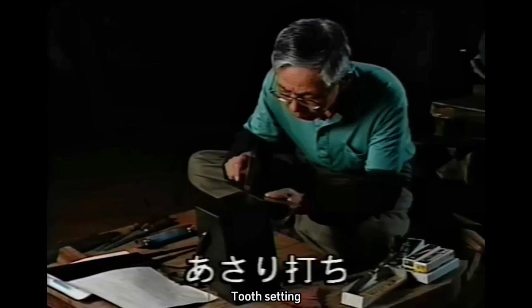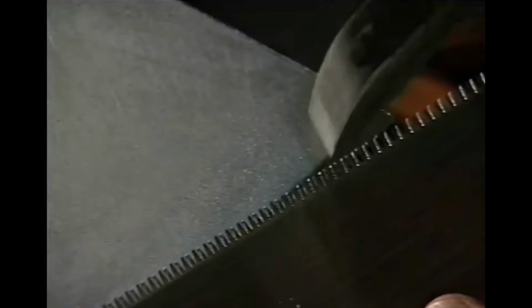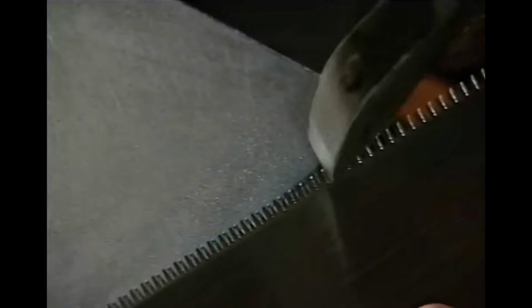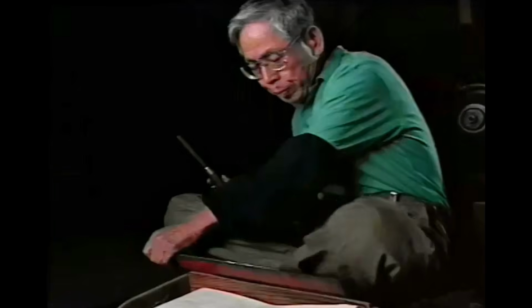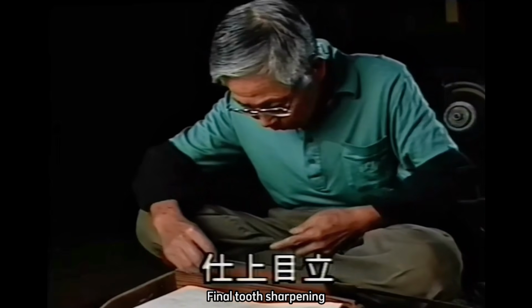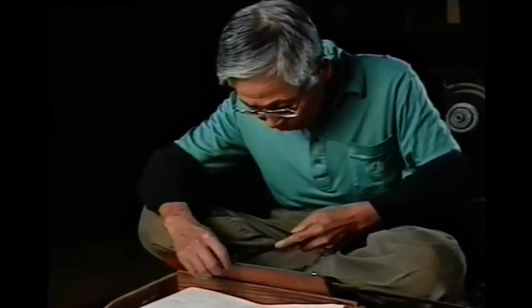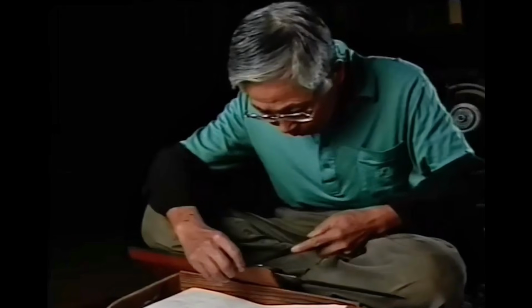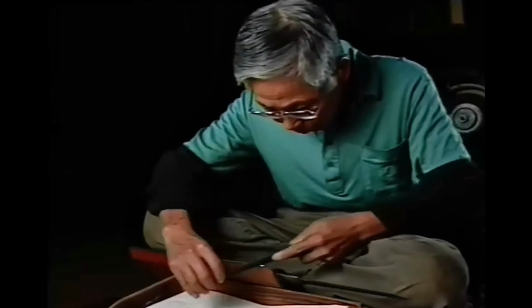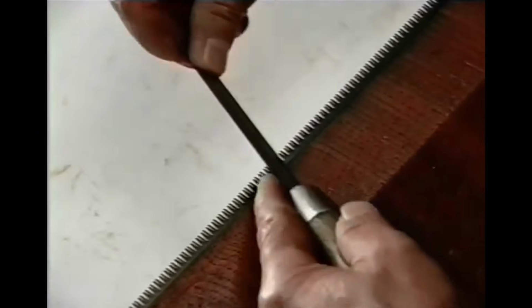The teeth are struck alternately to create the set. Striking every other tooth on the edge of the anvil requires a delicate sense of touch in the fingertips. Final tooth sharpening is carried out with a fine-toothed file. Just as with the set striking, every other tooth is filed in turn.